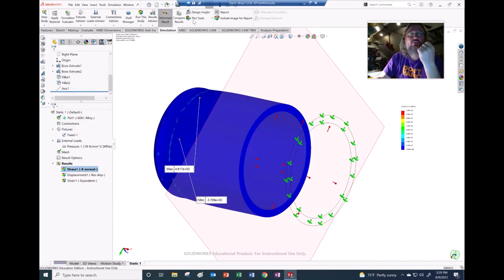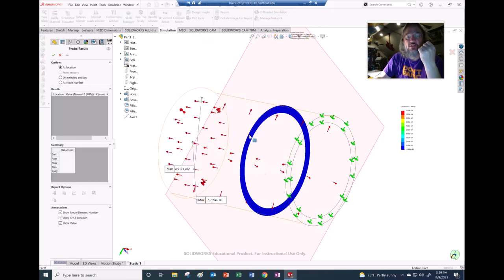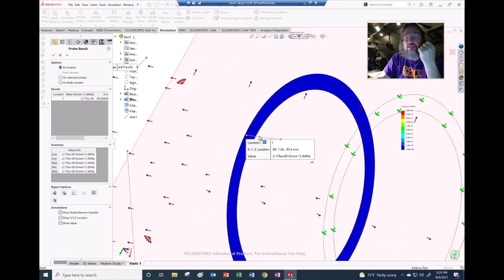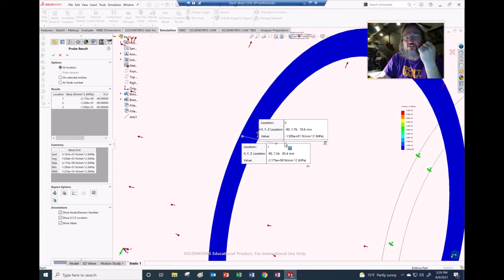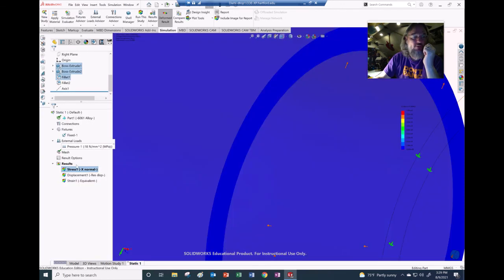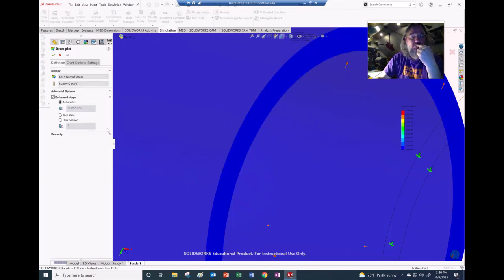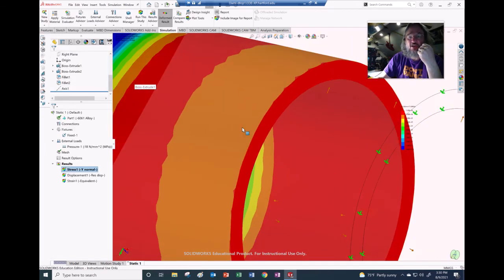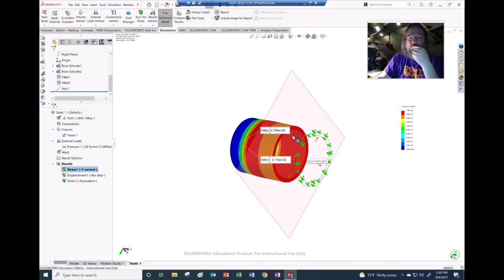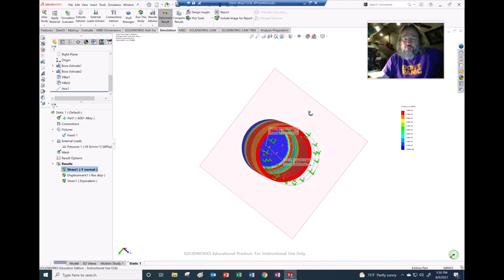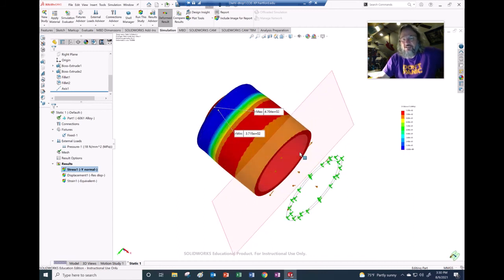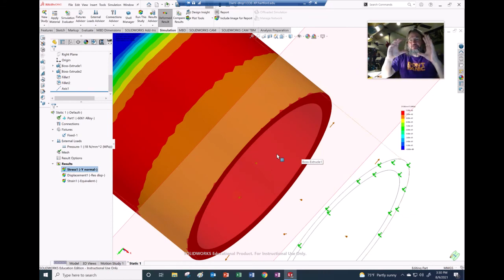Yeah. So if we go to plot tools and the probe, and pick some place on there, we could see that it was really small. Okay, so right there, see it's getting negative. It's getting close to that. It's like negative 16, there you go, negative 16.75. We're right there. It's like 18, basically, right? So under the X direction for this, the Y direction must be the normal stress here. That should give us a pretty good interpretation of the hoop stress. And once again, it's messed up because of the end right in there, but the thing is expanding out in this direction.